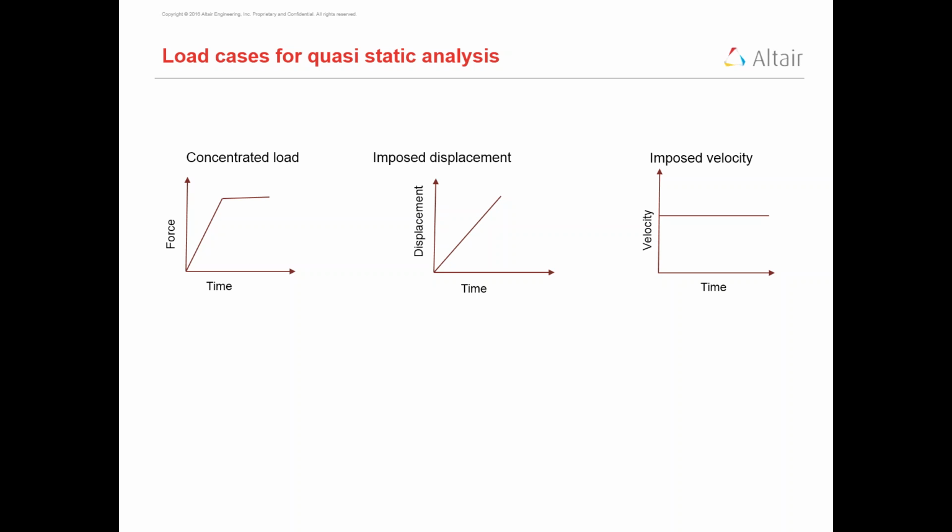There are some cases where we start from 0, 0, we ramp it, we hold it, again we retract it, and so on. But generally when you are applying an imposed displacement, it should start from 0, 0 and we ramp it. Now I will demonstrate how to apply imposed displacement in a quasi-static analysis through one example.